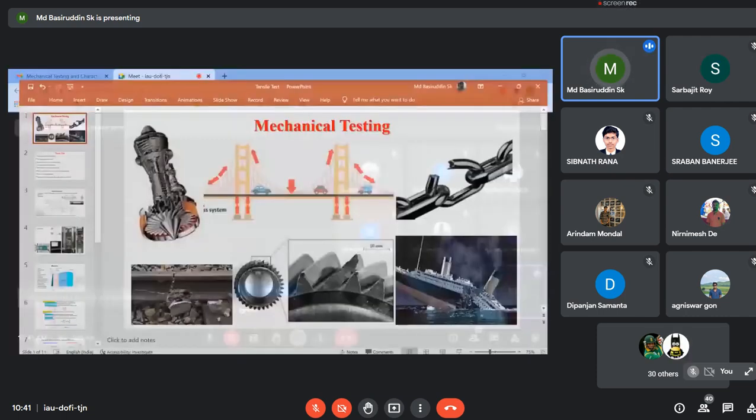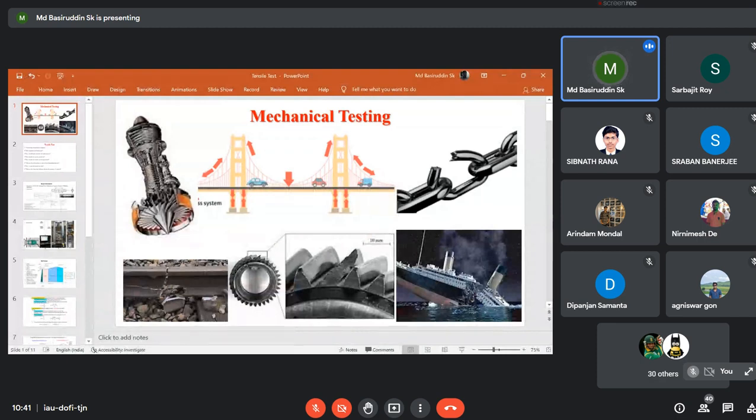But when they went through the joining process, they again came back to the initial position, like with casting methods, because at the joining points some material has to melt, and then the melting pool joins together, and in this way joining happens. So again, the microstructure at that particular region was a cast microstructure. If you know a little bit about the difference between cast microstructures and heat-treated or processed microstructures, then I think it will be quite clear to you.